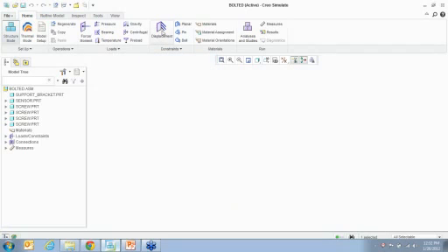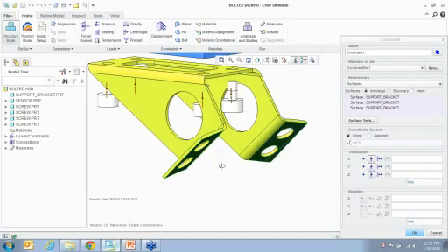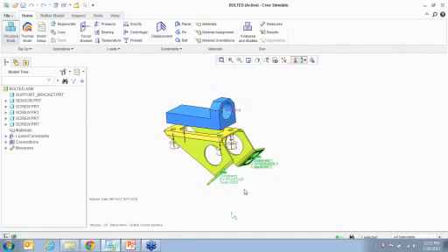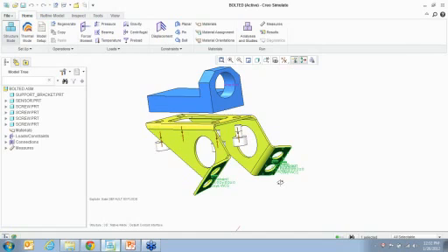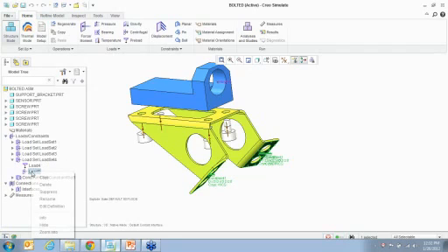Then let's say displacement, we're going to go ahead and fully fix these particular surfaces. So fully fix, I don't want them to move. So right now we're pretty set to run an analysis. If you run an analysis right now, it's going to tell you what happens if all the 4 bolts and the load are applied at the same time.